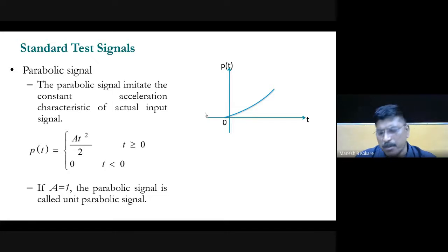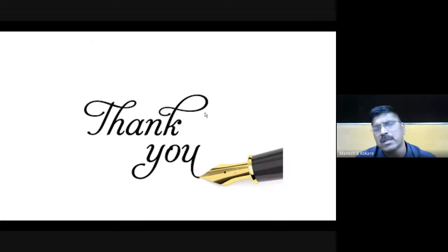your impulse signal. So as I said, generally the impulse signal is used to find out the transfer function of an unknown system, and then the step signal, ramp signal and parabolic signal are used for testing that system for sudden change, constant velocity and constant acceleration. So that's why all those signals are considered as the standard test signals.